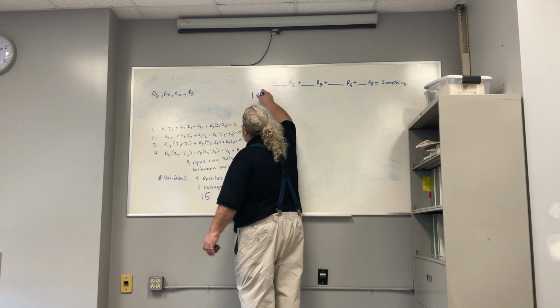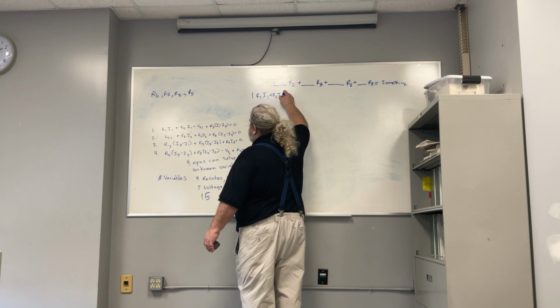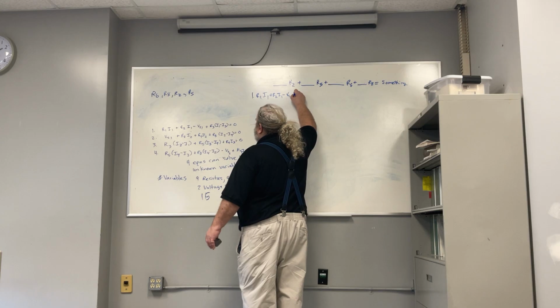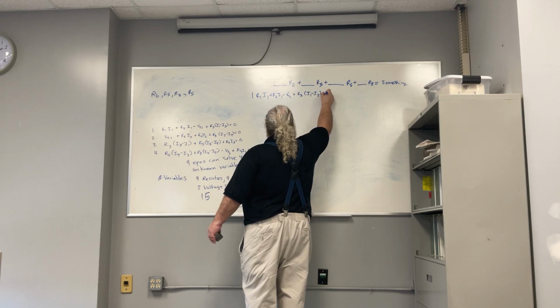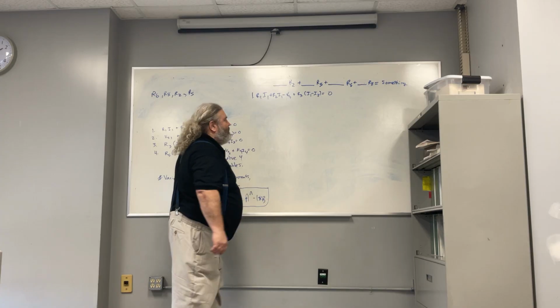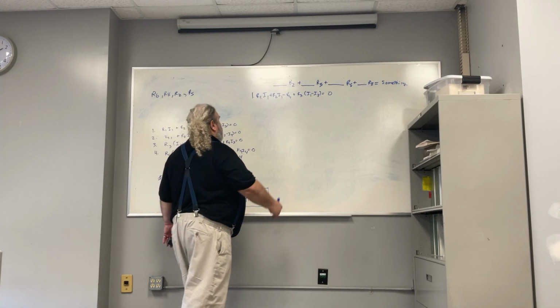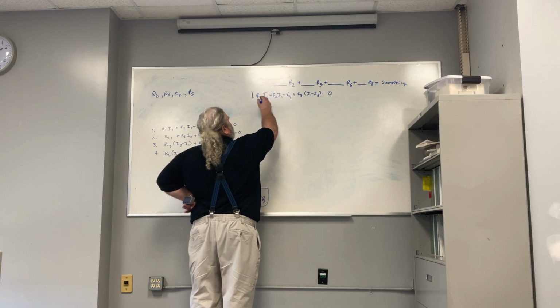We're going to write this out. It's R1I1 plus R2I1 minus VS1 plus R3(I1 minus I3) equals 0. Okay, do we have any R2s? Okay, so what do we put here? Oh, I'm sorry. What do we do with this? Are there any variables in this?